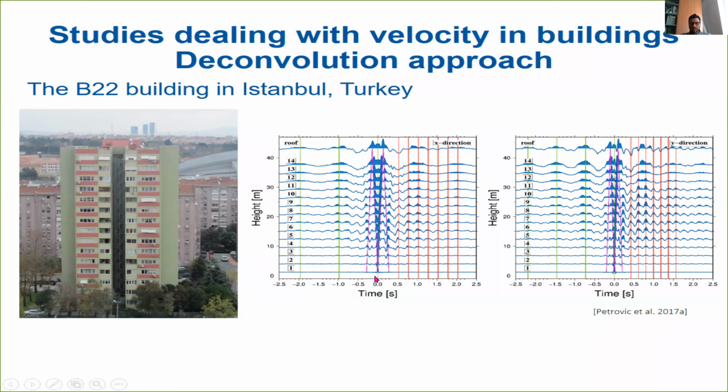We could identify, for example, a clear upgoing wave reaching the top here in violet, coming down, and then becoming much smaller later, while we could clearly observe different oscillations, also with different frequencies, for different heights inside the structure.